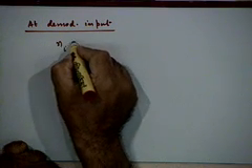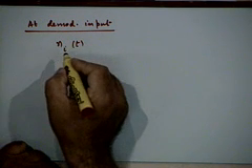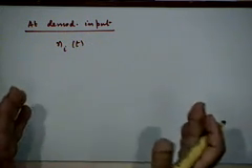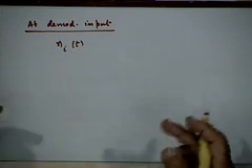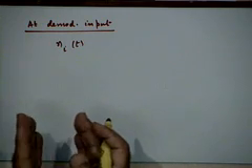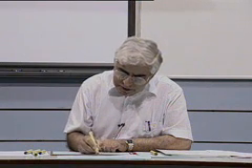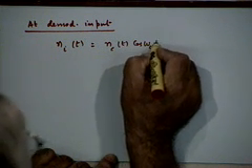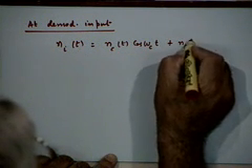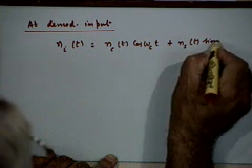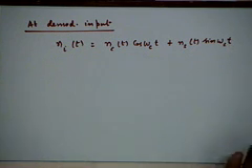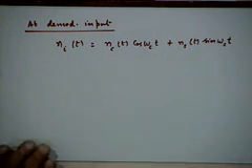The noise n_i(t), when I say i, it refers to input, but what point in the receiver? After the band pass filter, input to the demodulator, right. Remember that. So, this again can be written as n_c(t) cosine omega_c t plus n_s(t). So, there is no difference here as far as the representation goes. Representation is still valid, right. It is a narrowband noise process, it will have this representation.